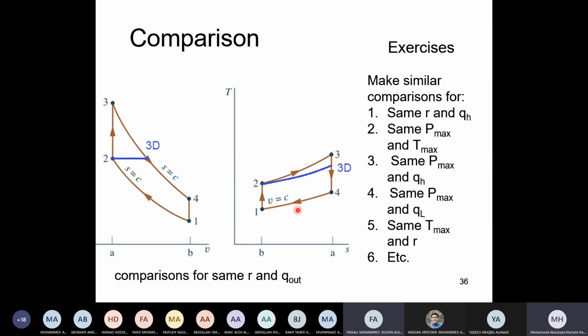Okay, so now this is one similar. If this was a Carnot cycle, it's 1 minus TL over TH. TL is the same, but here TH for the Otto cycle is more than the diesel cycle, and therefore the efficiency will improve.